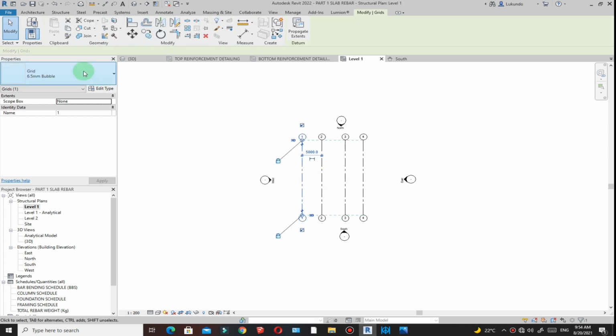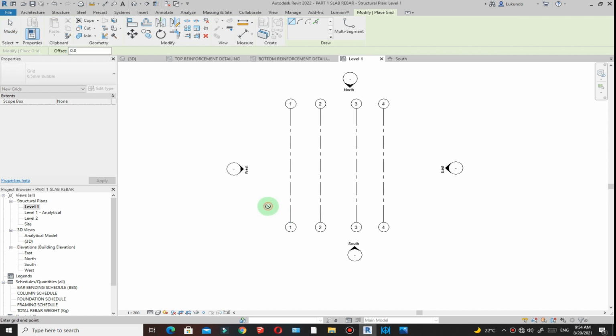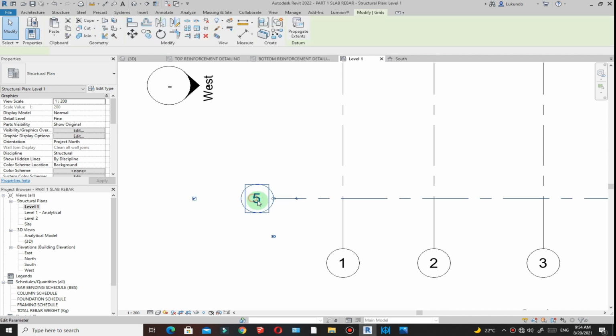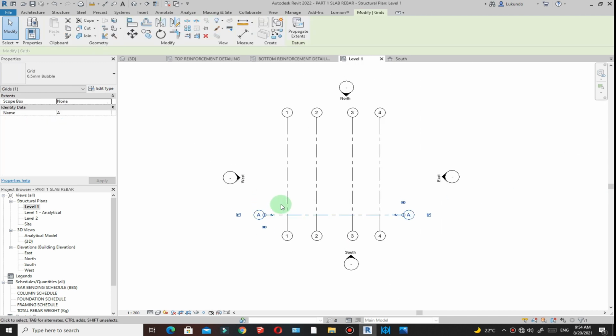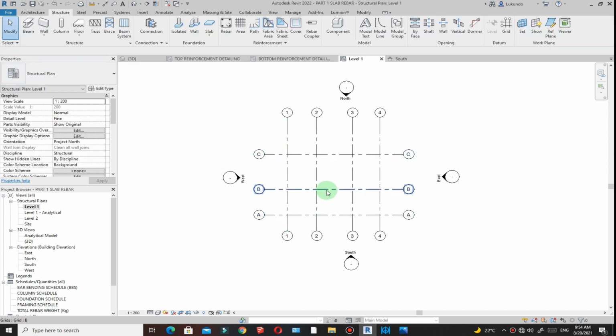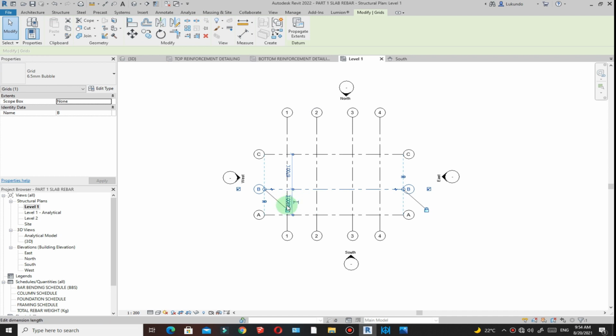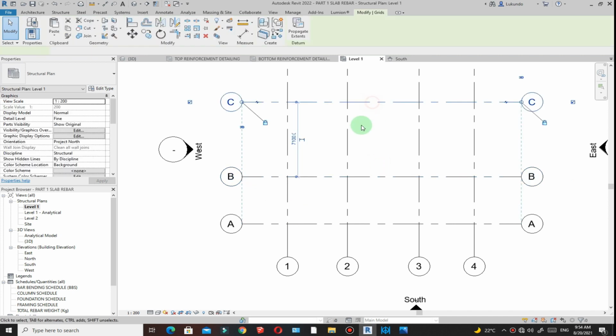Then I'll click on that grid. I can go to structure there, click on grid there. Then do the horizontal grids, the first point, second point, modify. Double click there, start with A, click outside. Then select on that. I can copy if I want by clicking on that point and just have 2 more like that and click on modify. Then I'll select on that and I'm just going to have 4,500. You can type 45 if you want, click outside.